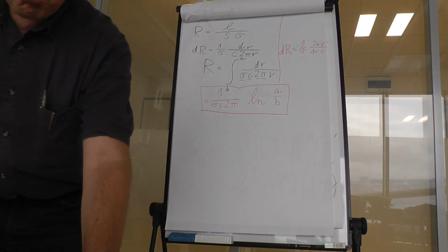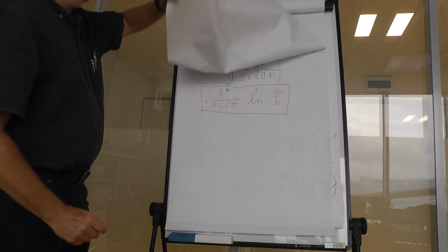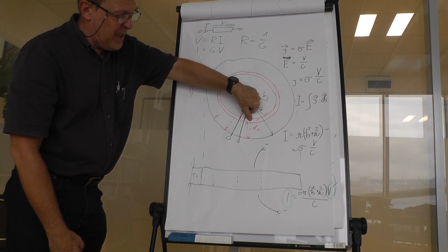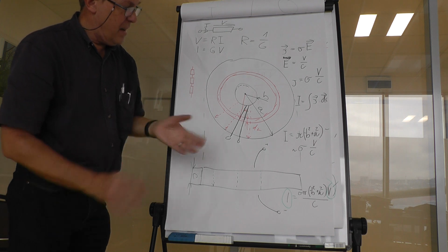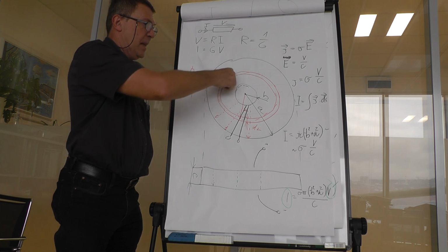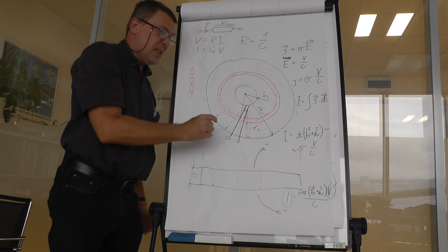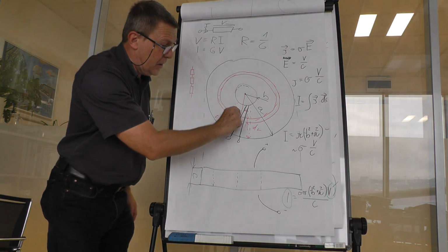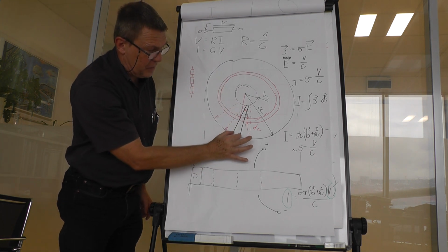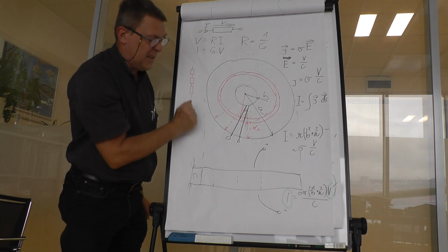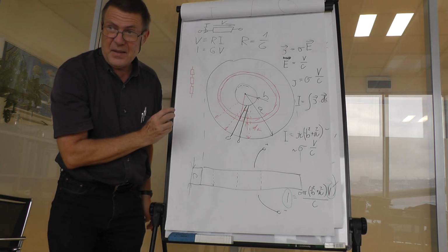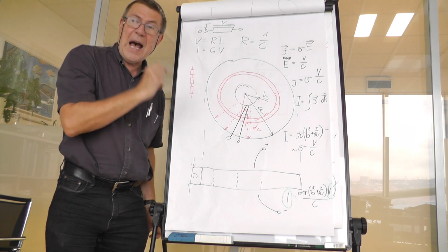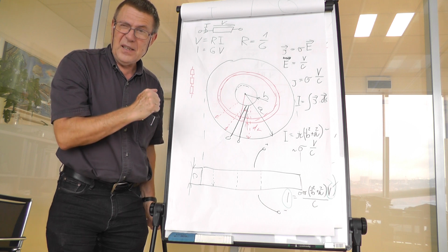Now, there is a second important point we have to discuss. In our first inhomogeneous case, the current was flowing in this direction so that those differential resistors have been connected in series. But now we have established an element in which the current flows and does not interact with the other current in another layer. So in fact this is not connected in series, but all those current paths are connected parallel to the metallic electrodes. So now we have a set of resistors, differential resistors, that are connected in parallel. But as you know, when connecting resistors in parallel, you can't simply add their values. What you add is not resistor values, but conductance values.